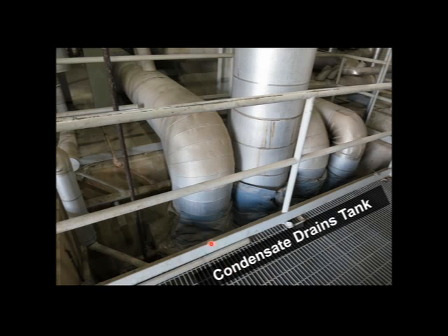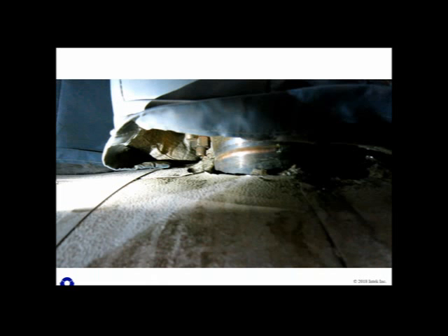There is a controllable steam valve into here that they can control the steam pressure into to try and purge the system out. And that's the reason for it, there was a leak in one of these valves. So let's take a look at where the leak was. Again, this was found with the helium leak survey.